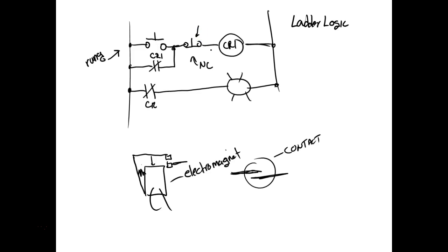So y'all see this all the time. You go up there and you see a start button, you press it and release it, and the motor keeps what? Keeps running, because why? It sealed itself in. So I'm sure at Rosa you see a lot of push buttons. They probably simulate them on a lot of HMI panels. But they still have push buttons, like e-stops and stuff like that. You can't simulate e-stops. E-stops cannot be software. E-stops have to be hardware. They've got to be hardwired.